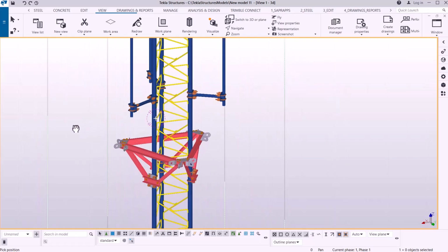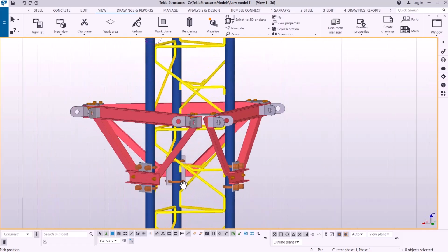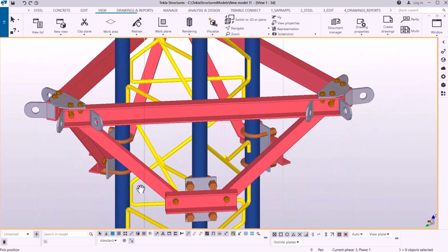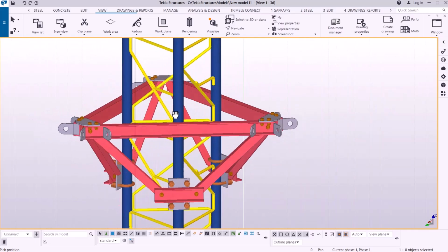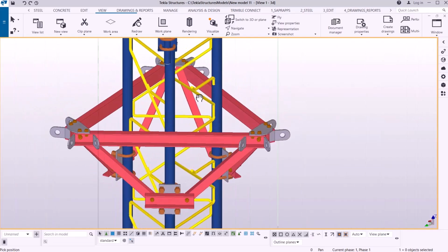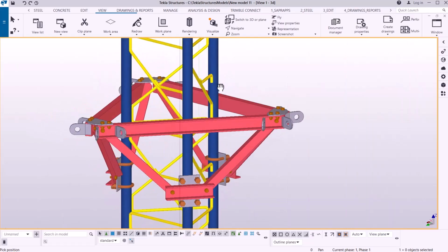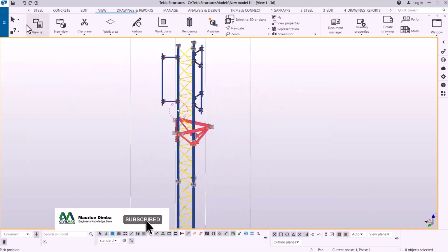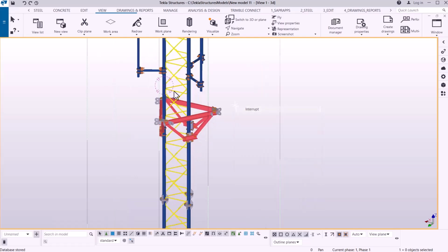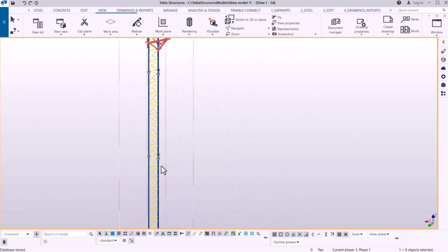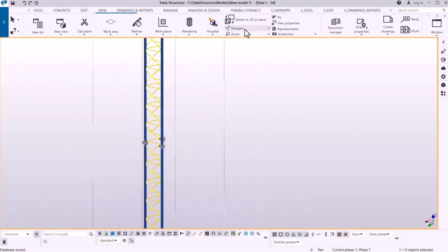So the anti-torsion fixture will come up here, and I will also check whether we have some clashes here, and there is some, but they are rectifiable, and in this particular case we're not in any way colliding with the braces, the rod braces that are anchored or welded between the three legs. So we have this in place. So the number one thing you always do, remember to save your work. There are quite a number of anchor plates in here, but that will be done in the next presentation.